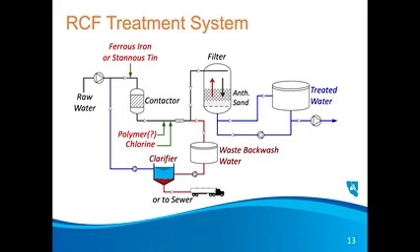You may have to add a polymer to make the material a little more filterable. You add chlorine, and you go through a regular sand anthracite process to collect the material you just filtered. Go to treated water and then pump it out in the system, and use treated water to backwash the filter whenever turbidity starts to show up on the effluent.